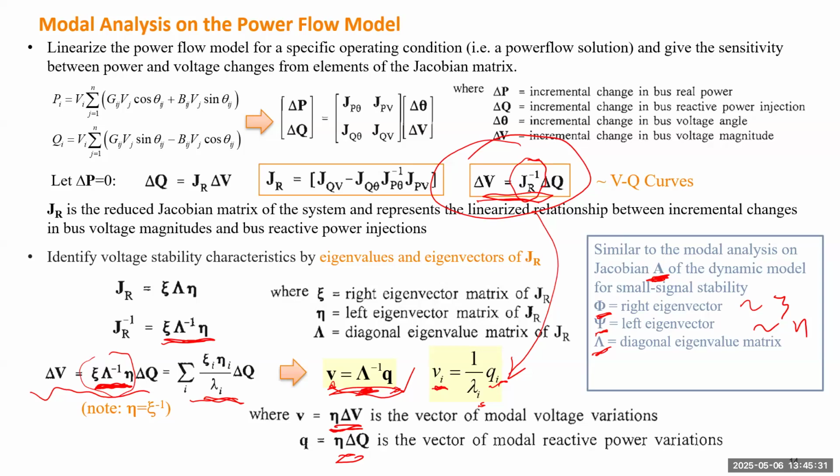Okay. So if you pick any single equation here with any I, that tells you the VQ curve for each individual mode of voltage stability. That has a similar idea to this equation. Remember, for small signal stability study, we utilize the diagonalization and decompose the system regarding the eigenvalue. Finally, in the new space of Z, each Z state variable is independent from any other variable.